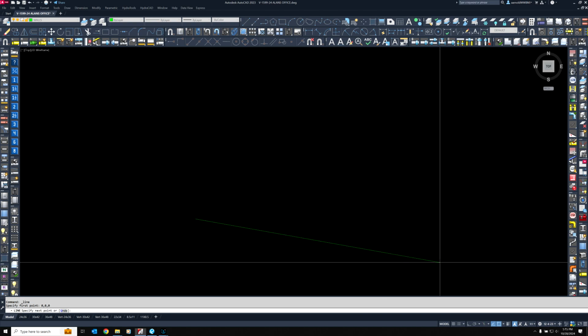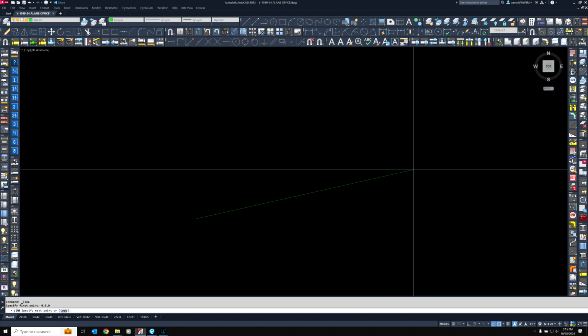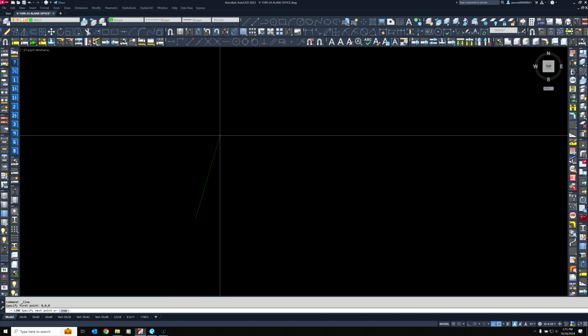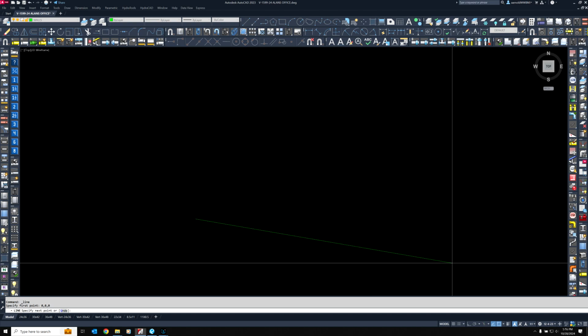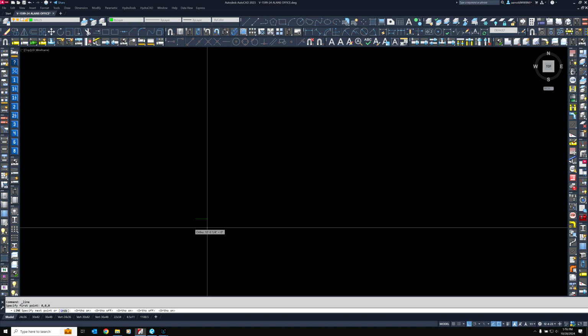Next thing you want to do is, we're not drawing a square building, we're drawing something rectangular, with straight lines, when the program is drawing at open angles right now. So what we do is you either toggle it with F8, or there is a preset on your mouse thumb buttons. But right down here you'll see Ortho mode. We're going to toggle that on, and you notice that locks so that it can only be perfectly horizontal and vertical.